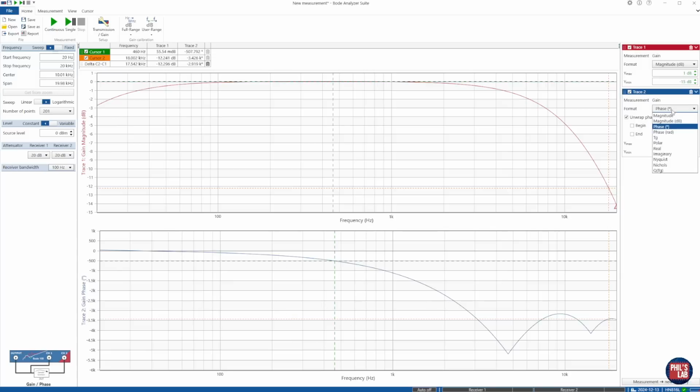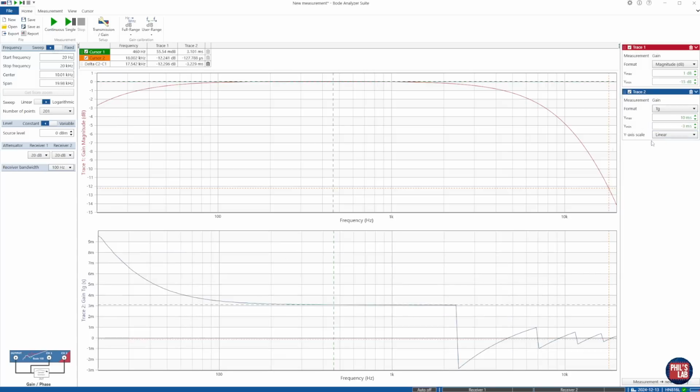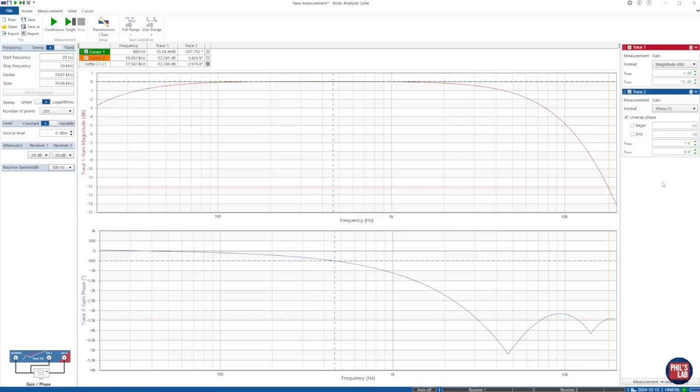We can also on the right hand side change from phase to group delay, and we can see the overall delay versus frequency. Of course this isn't helpful if we're trying to actually measure what this filter is doing, because the effects of the filter might be dominated by the overall system response. So we just want to measure the response of the filter and de-embed the system. The way you can do that is calibrate with the pedal on, but with no effects being applied. So we want to characterize this system and null it based on this measurement.